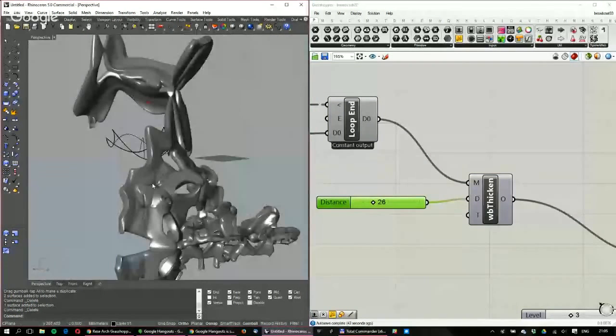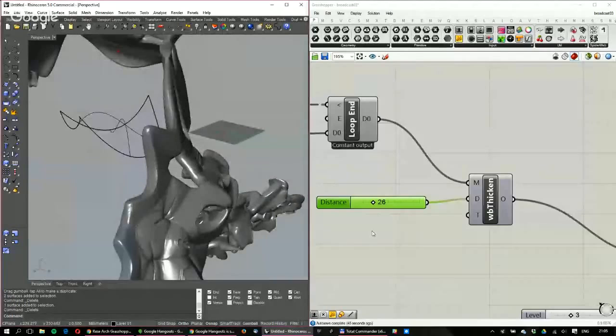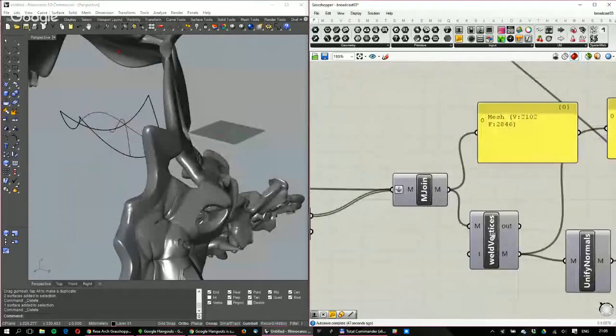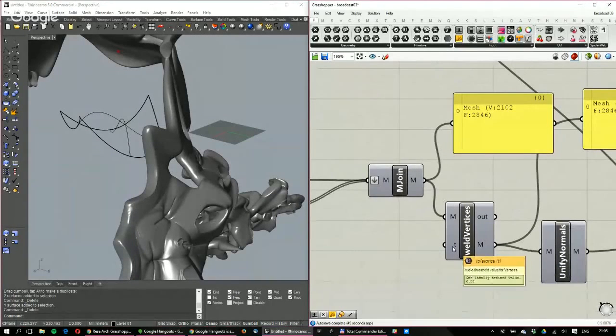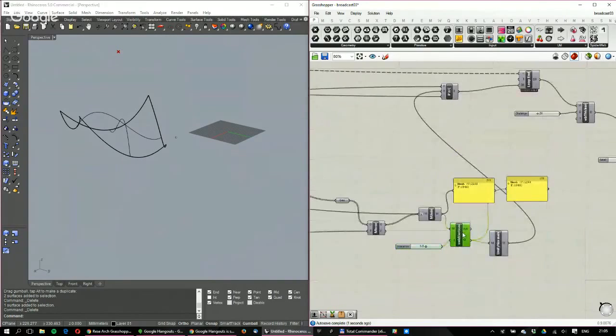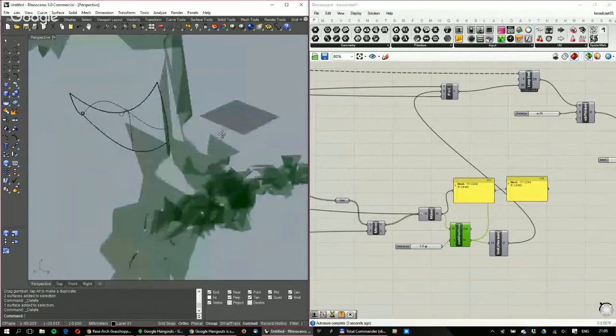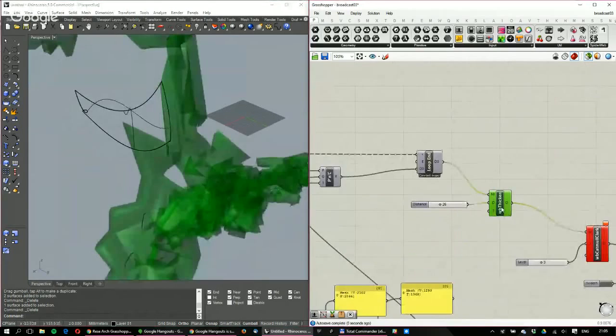Mesh geometry modelers, when they use the weld, just like we do here, usually set a certain tolerance. And I see there is one, so let's increase the tolerance to, let's say, 5.0, which welds all the points that are close enough to each other. How does it look at the end? Well, it doesn't really look so good.